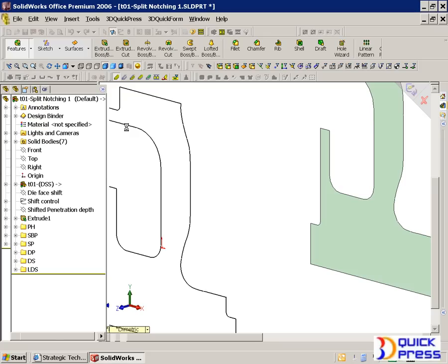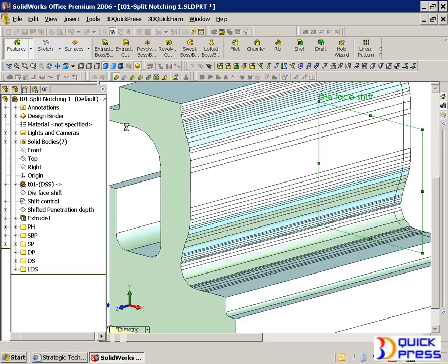So finally, it's going through and finishing up. Now it's going to bring in that last thing that I did that was custom for that one punch. It's going to bring in that custom retaining option that I specified for that one punch. It's going to look for the longest non-cutting edge, and it's going to align itself to that edge. It's going to automatically know that it's on the bottom of the punch holder because that's the way that template is set up. Well, the punch holder can be at any level per job. Well, in this case, it knows the current level. That's the whole beauty of the automation.